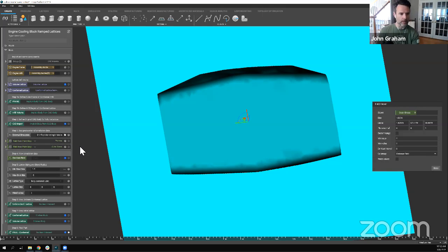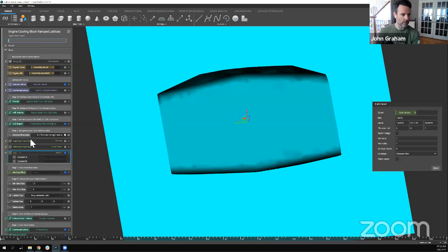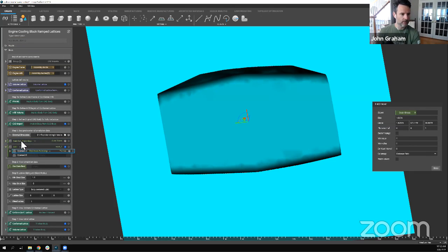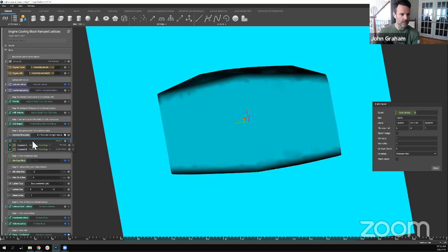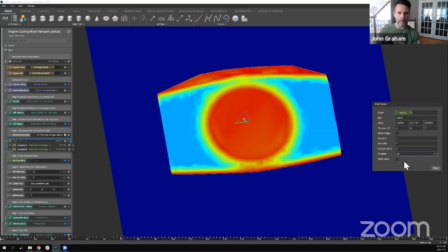How could I integrate those two together? Well, what do you do with fields? You can do anything you want with them. In this case, I'm going to add them together, which is just the merging of these two, right? So if I look at the data now, and by the way, these have been normalized. So of course the units are completely different, but what I have done is mapped the highest stress value with the highest temperature and said that those both have the same values. So I've mapped them together and they line up nicely. And the same with the smallest values too.